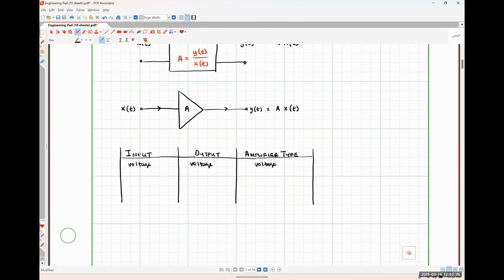Anyway, the signal that our antenna picks up is typically on the order of just a few millivolts. The further we are from a radio station, the lower that number is going to be. Well, the preamp stage of that audio amplifier is going to effectively boost those voltages to what are called line levels that will then go into a power amplifier stage that's used to drive your speakers and things like that.